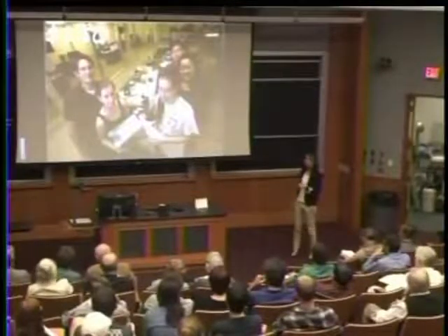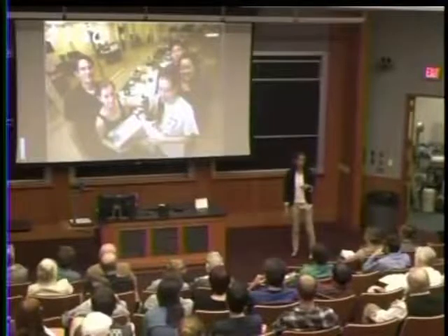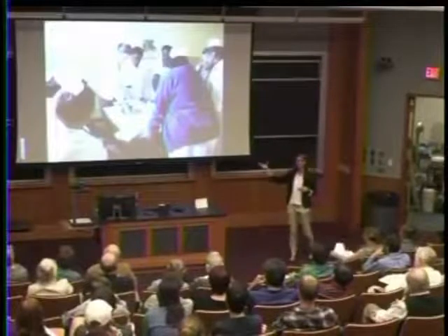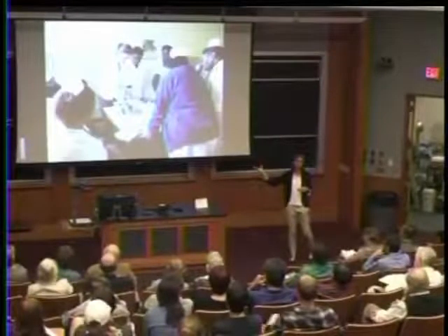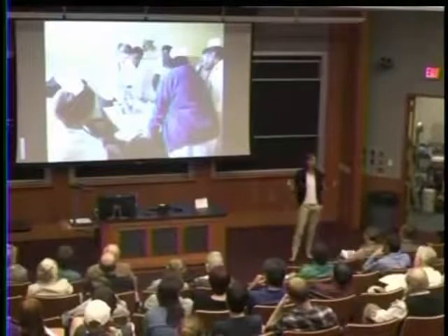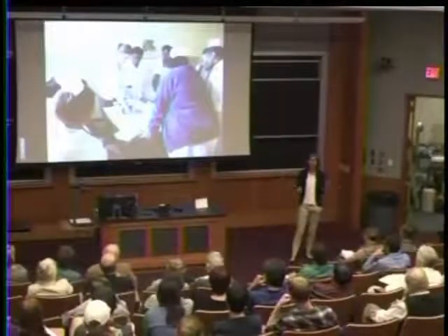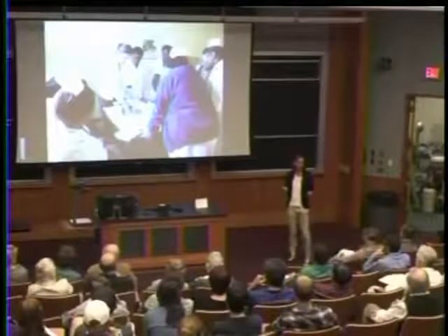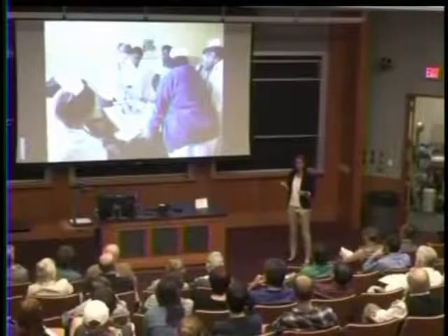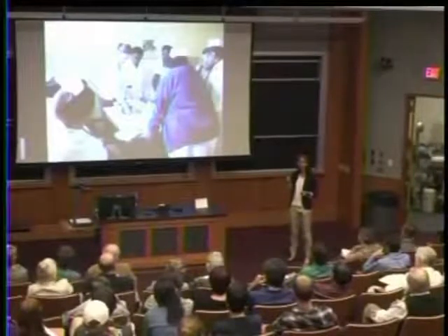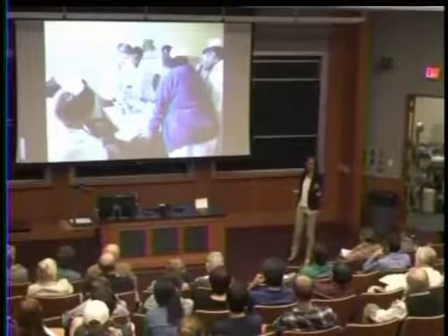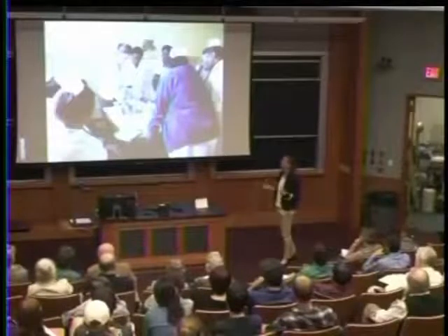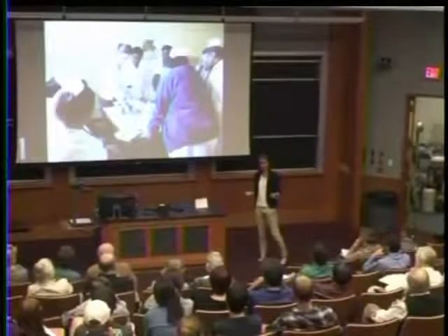And so the woman that you see here, Jocelyn Brown, traveled on an international internship the summer after she graduated to Malawi. And she demonstrated that system for the nurses who work in the NICU. And they told her everything that was wrong with the device. They said, this plastic box, it is going to break. They said, your device is designed for a 110-volt system, we have 220 here, your step-down transformer is going to disappear. It's too complicated to plug some of the tubes in the front and some of the tubes in the back. The icons all need to be pictorial. But can we keep it and use it because we really need it?